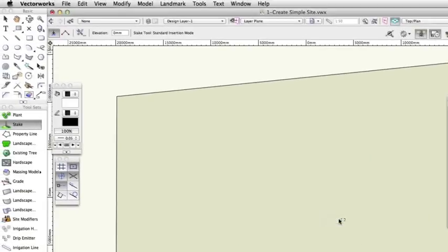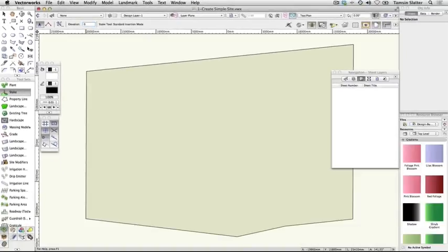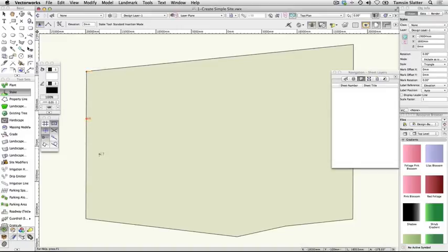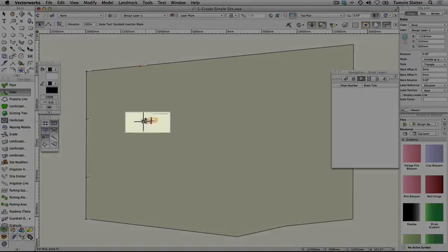On the toolbar, change elevation to 0 and press Enter. On the left edge of the polyline, click at the corners and 2 points in between to create 4 stakes that represent the elevation of 0. On the toolbar, change elevation to 1000 millimeters. Roughly 1/4 along the length of the shape, place a vertical line of 4 stakes. Notice the new elevation is displayed by the stakes marker.